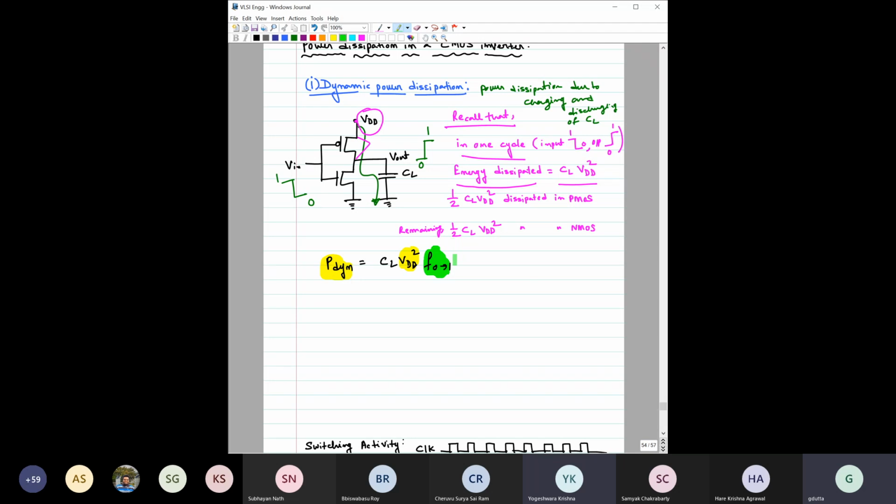So we will arrive at some situation where the total circuit performance would be limited by the dynamic power dissipation because of this very high clock frequency. So probably that will also restrict us, and explain why we cannot further increase this clock frequency.